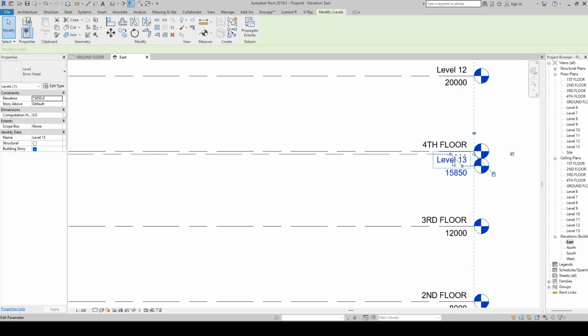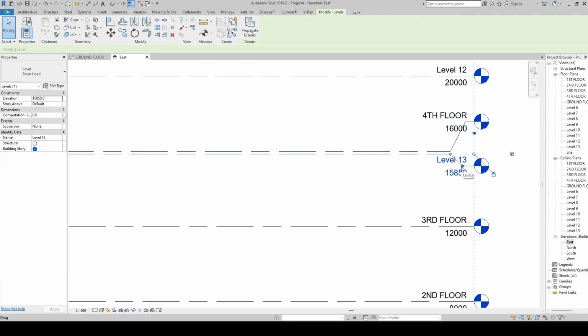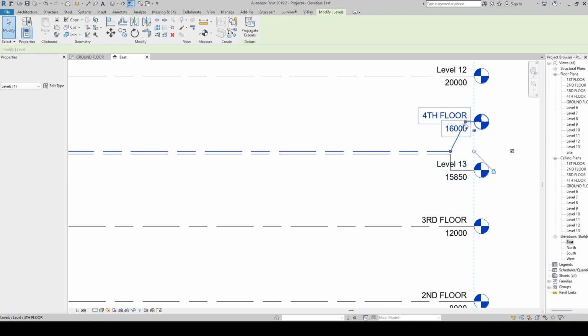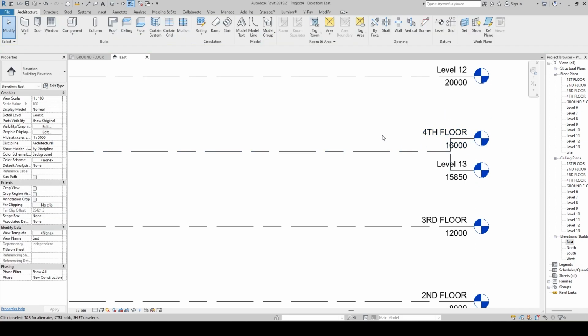The level head is going to drop this way. Again on the top you click on this, and both will drop this way. There are two dots available. You take this and drag and drop. See, this has gone up. Again, if you want, you can drag and drop, or do this styling here as well. This works when you have multiple levels in particular floors. What I told you right now is going to be useful for you.